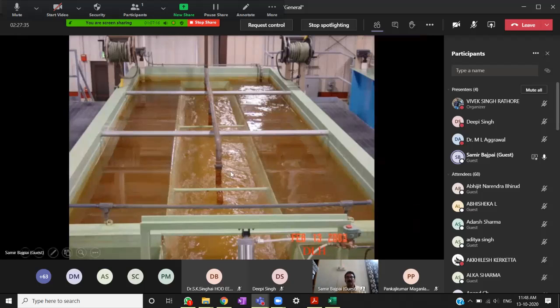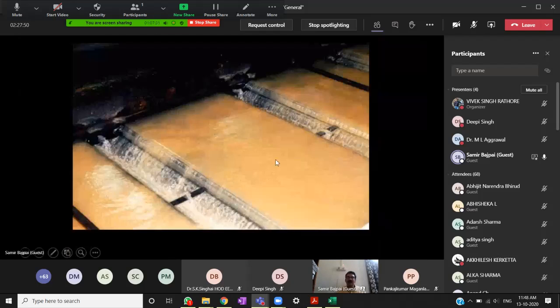So this is typically where backflow cleaning is taking place. So you are agitating the filter bed, and this water is coming into these channels, and dirty water is taken out. This is another diagram for backflow operation. So you have agitated the whole filter bed, the media is separate, and this impurity being light in weight is coming away in this backflow and taken to the surface troughs.